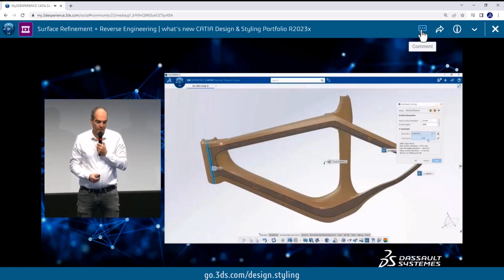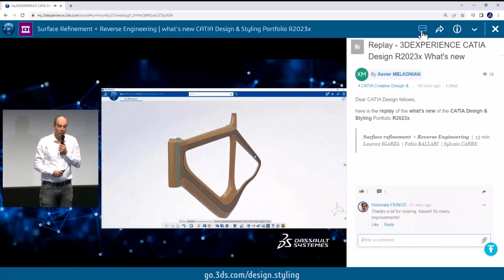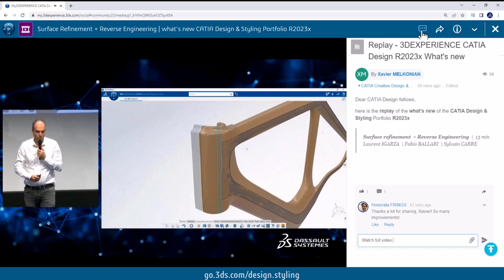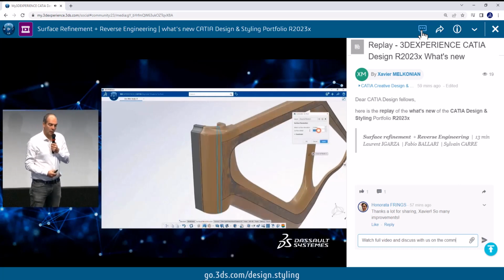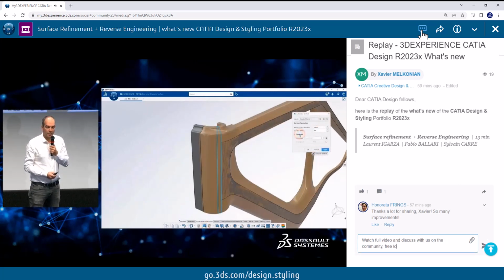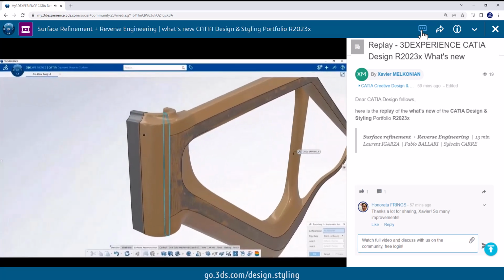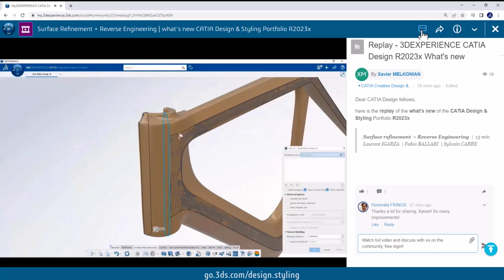And at once I get this surface with a flow following the characteristic line, which will be more obvious after the fact to modify it or tune it in a subdivision modeling world if needed. Okay, so here I will do it also on the symmetry plane, and so I'm also able, if needed, to select boundaries of an existing surface to provide the tangency condition I need on the symmetry plane. Okay, so you can see that we have, of course, selection propagation within the join or within the boundary to avoid clicking any curves by yourself.